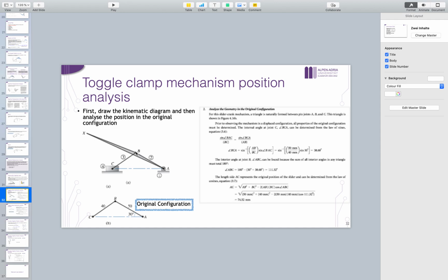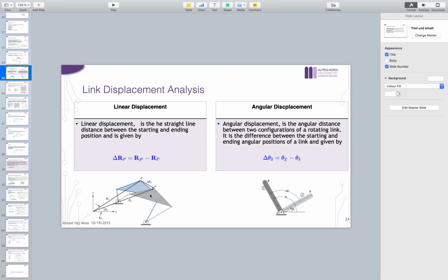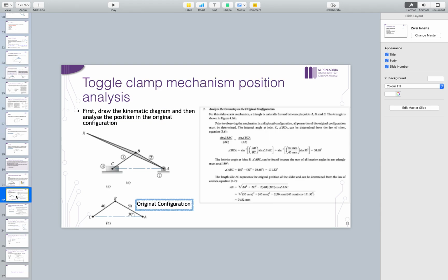It could be wider, for example, but what is important is that it shows the link is complex and has points, and that you are connecting it to the middle of that link and not to the end. I was just wondering why this is a bigger triangle than this one. That's not important. What is important is the dimension. If you are doing graphical analysis, the distance between AB and BX is important.